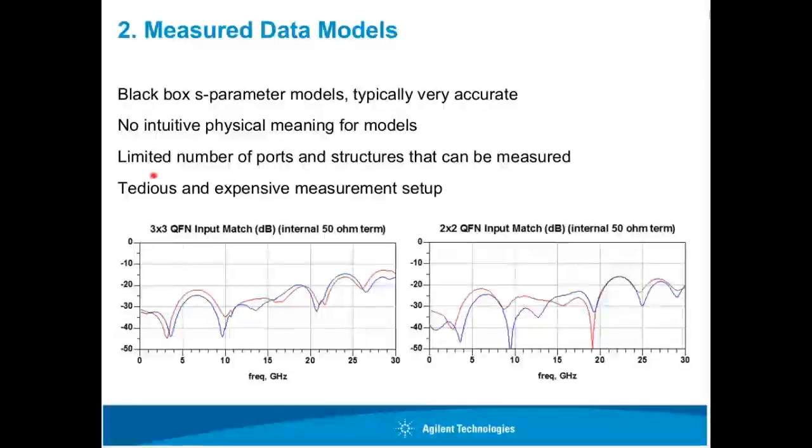In terms of the number of ports this model can handle, it is limited by the number of ports the instrument can measure. Also, if we go into certain special structures, for example, structures inside of the PCB or inside of the IC stack-up, they will be very, very hard to measure since there are only certain standard port configurations available for instruments. And the process itself is pretty tedious, and the setup of the measurement is pretty expensive. So these are the things we need to consider when we go with measured data models.